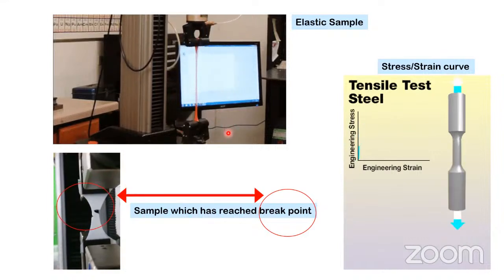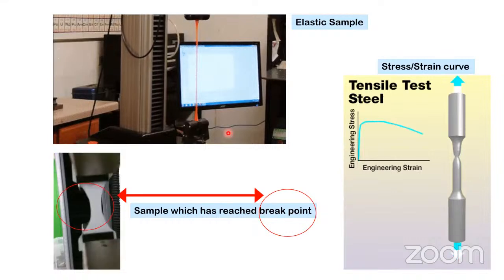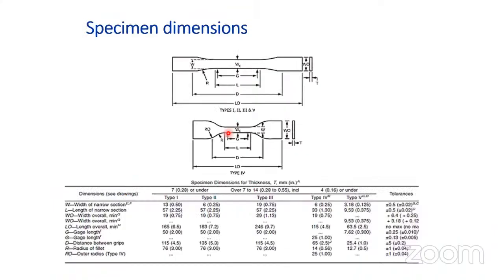Okay, so this is all about the tensile test or tensile properties of the polymeric material. Here we have given the standard size of your specimen, which is generally used to determine the tensile properties. As I have mentioned, dumbbell shaped specimens are used, but according to various standards the shape and size of the specimen change, and that shape and size are presented in this slide, in various dimensions to be cut for testing.